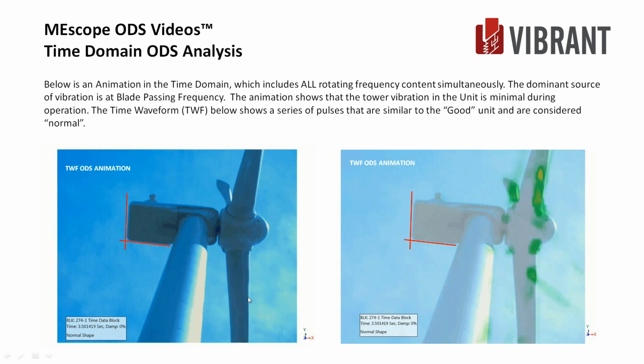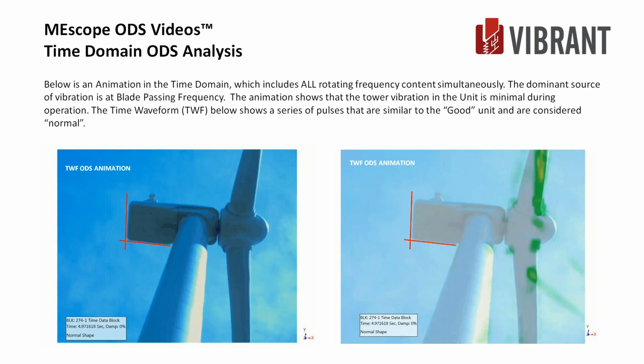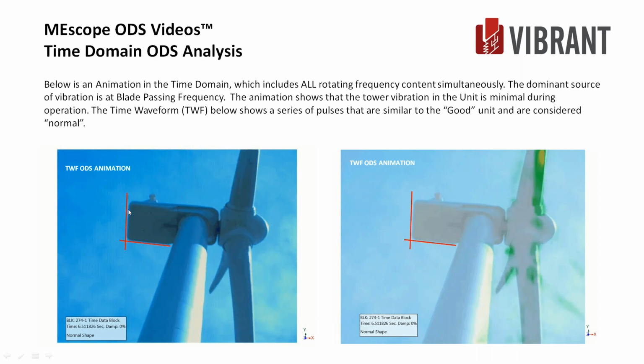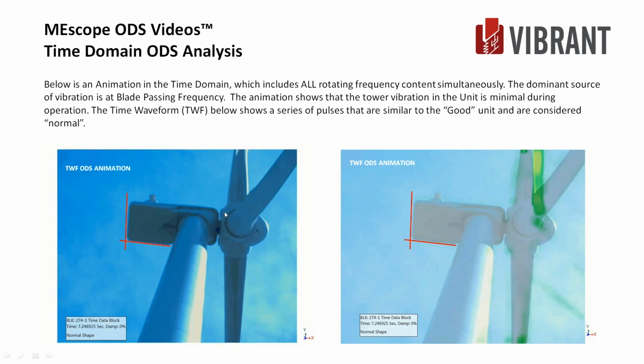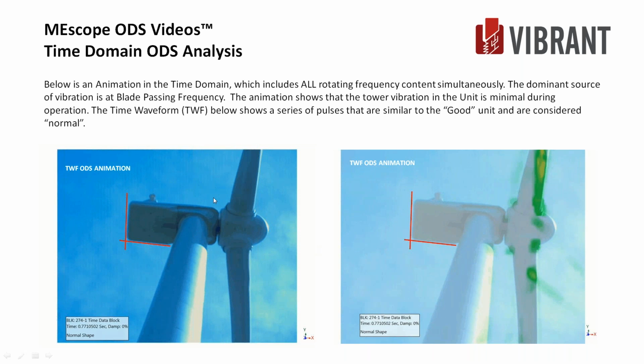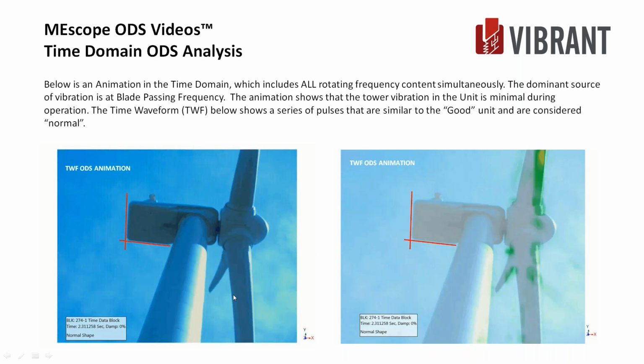So that's where you get that spring energy. You got a lot of wind force pushing axially on this structure, and when we tip those blades 90 degrees, it loses all thrust and we spring right back. So we're doing two things. We're the blade springing, and the whole tower will spring when you shut down like that.